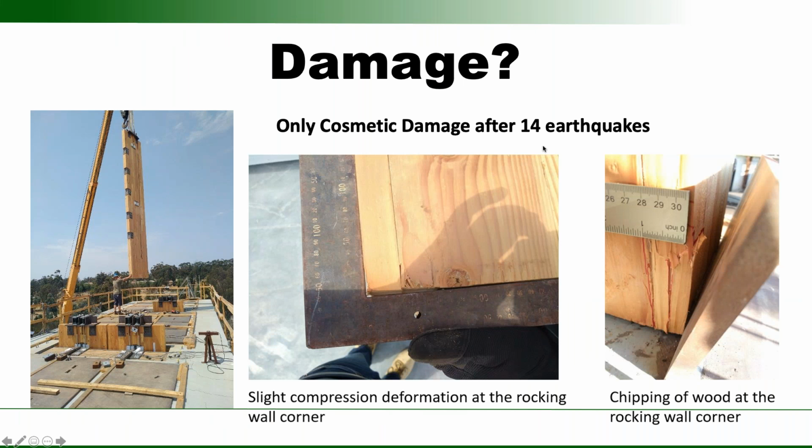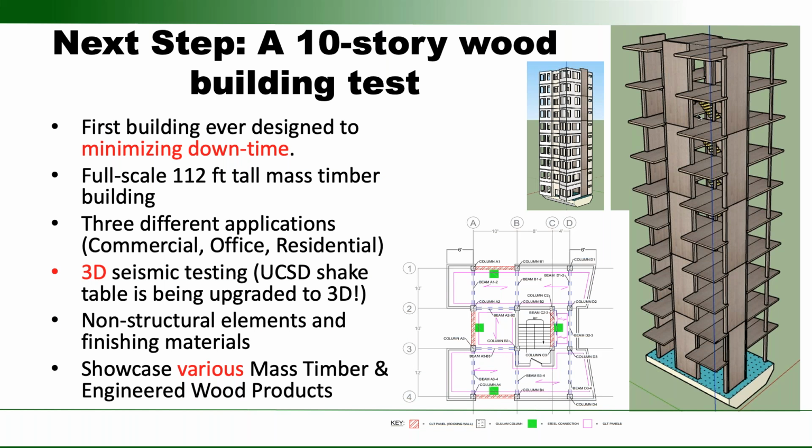And really, after this whole test series of 14 earthquakes, ranging from DBE to even 120% of MCE, the extent of the damage to the seismic force resisting system was some little nicks and cracks. So just excellent performance, and we're confident that the 10-story will work. So this is what it's going to look like. And again, the idea is to minimize downtime.